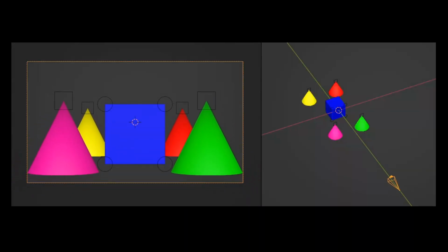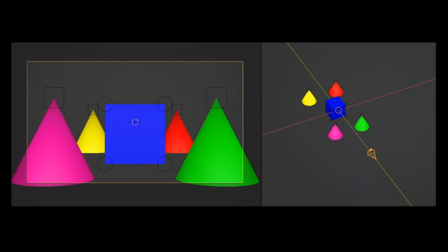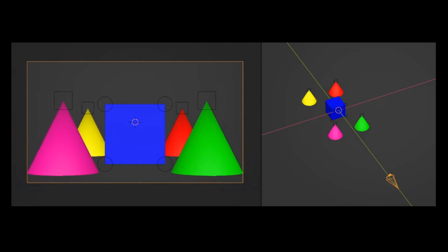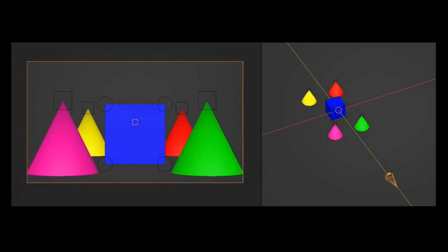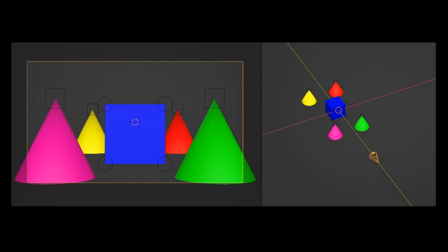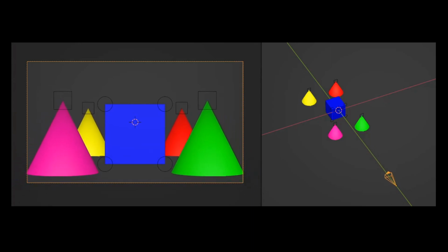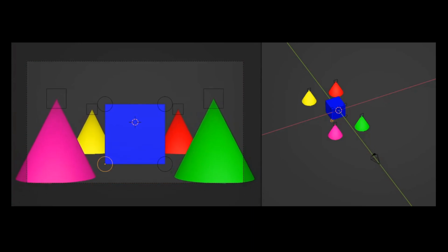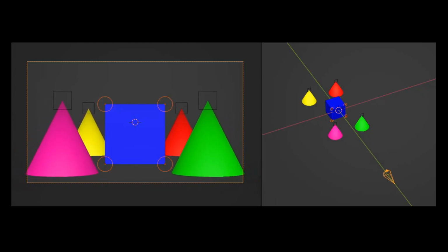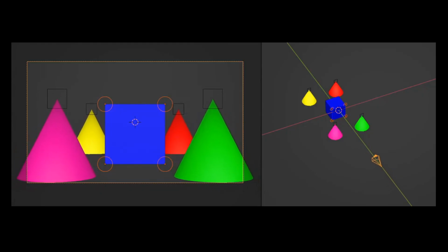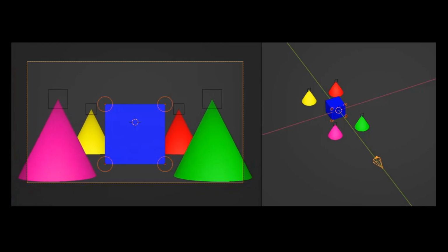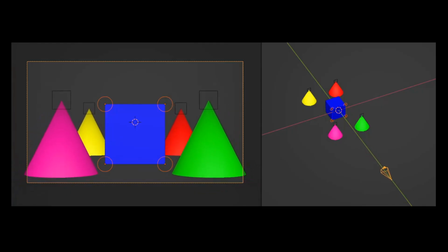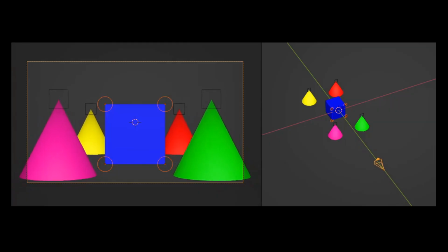Specifically for the focal length calibration, it is important that you place points at different distances from the camera. This is because if all points are at a similar distance to the camera, the solution is not well constrained, because there are an infinite amount of focal length and camera position combinations that will project the image in the same way. Look at the circles in this example. The camera is moving back and forth and changing its focal length at the same time, but the circles are projected in the same locations.